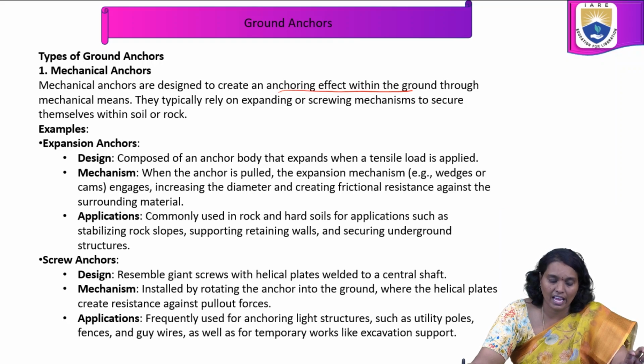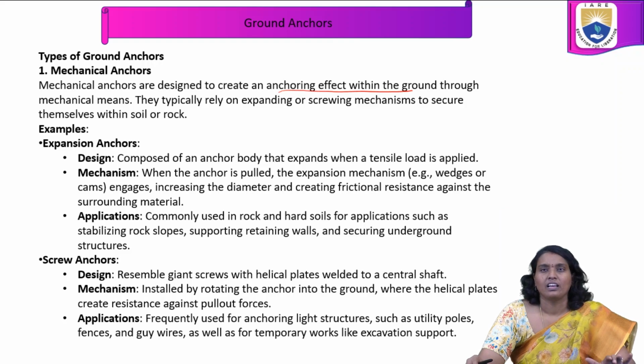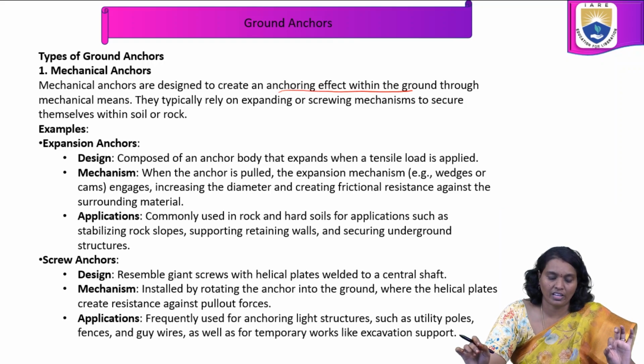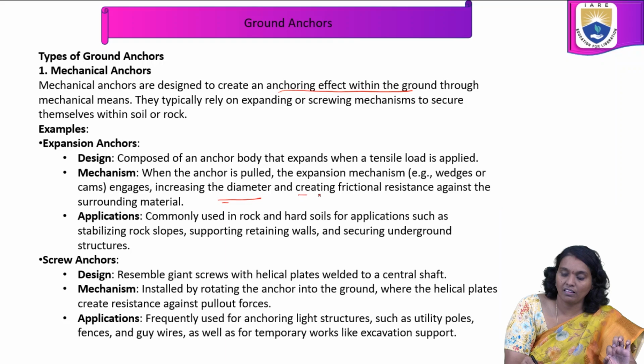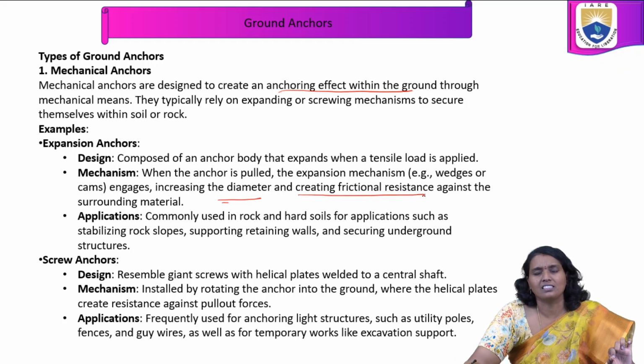Those are expansion anchors. Expansion anchors are designed with an anchor body that expands when a tensile load is applied. Whenever these expansion anchors are pulled, the expansion mechanism, the wedges or cams, engages, increasing the diameter and creating frictional resistance against the surrounding material.